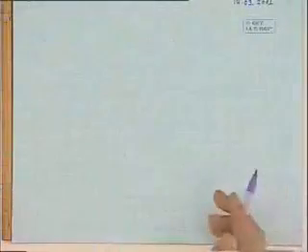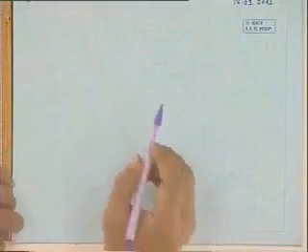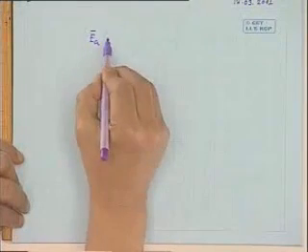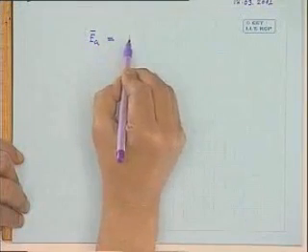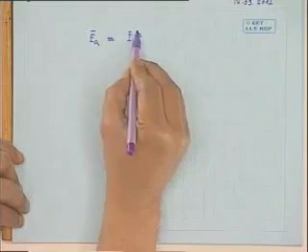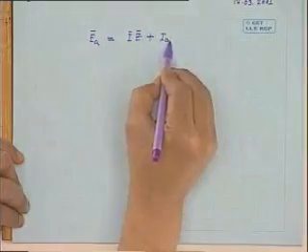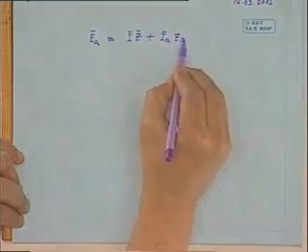From these two equations, you can substitute for V in this fashion, that is EA bar is equal to I bar Z bar, where Z bar is the load impedance and I bar is the total current, plus IA bar into ZA bar.